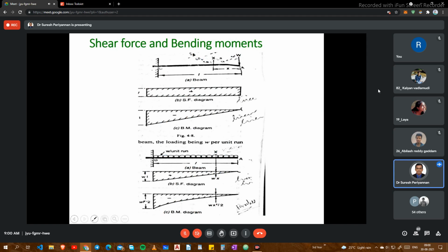Okay, just a recap. Now cantilever beam. In the cantilever beam, what kind of behavior is this? Linear behavior or line? This is a line. So I write it, so we don't waste time. Now see here, cantilever beam, the SFx, shear force with respect to x, we already know is equal to minus W. This is a straight line.